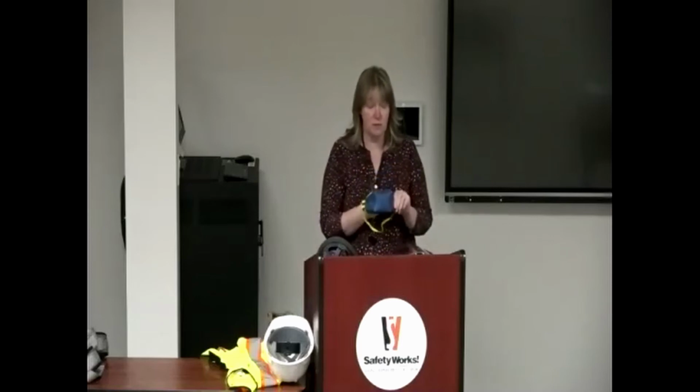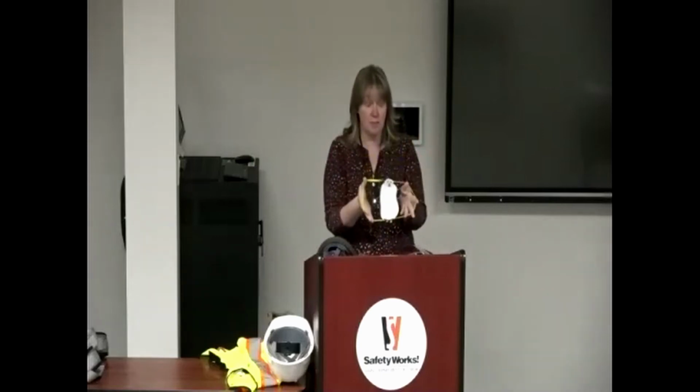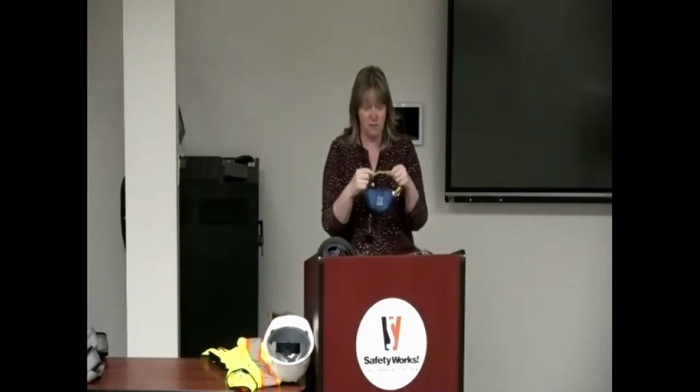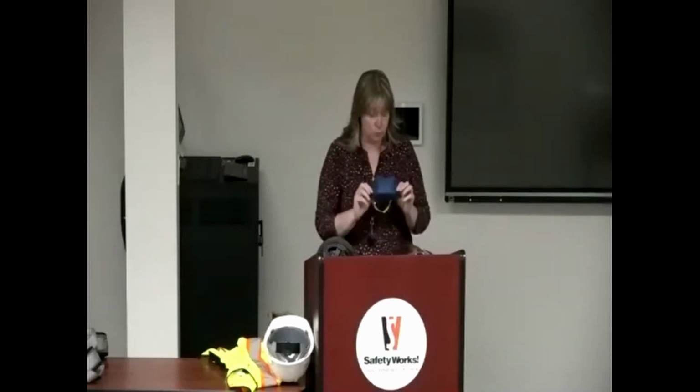People often call them dust masks or dust respirators. As you can see, a respirator will have 2 straps on a filtering face piece. If you just see one strap, that should be your first indication it might be a problem. They will have NIOSH on them, N-I-O-S-H, which is the body that certifies or approves respirators. So every respirator needs to be NIOSH approved.